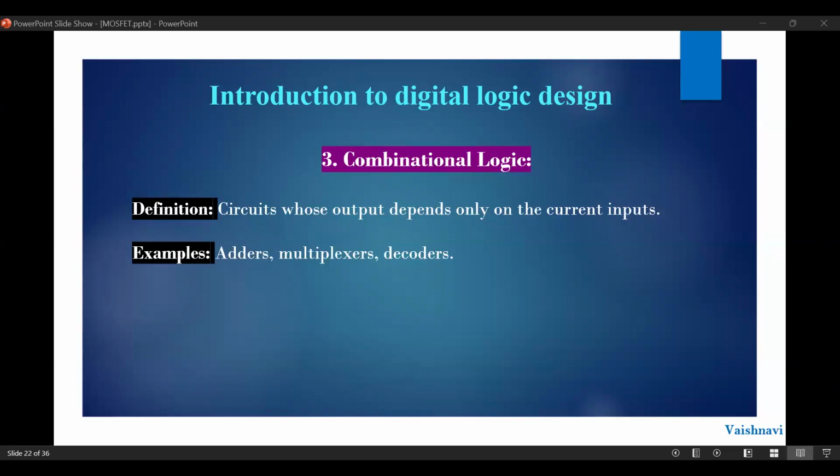Whenever you draw a combinational circuit, when we start learning the design process, you should know the specifications of what you have to draw, then the truth table, with A dot B, A multiply by B, A plus B, and so on. Then the Boolean expression, which is the output from the truth table. And for simplification, you know the K-map, and you need to write the number of gates here.